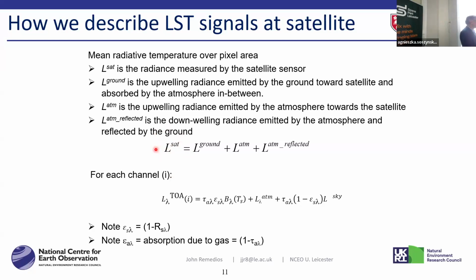It doesn't. What it does is it has photons falling on a detector, which generates a voltage or current. And people have already intervened to derive for you what we would call in the satellite trade a level 1, which is a calibrated geophysical quantity, something that's translated to radiance or brightness temperature from these signal detector counts.